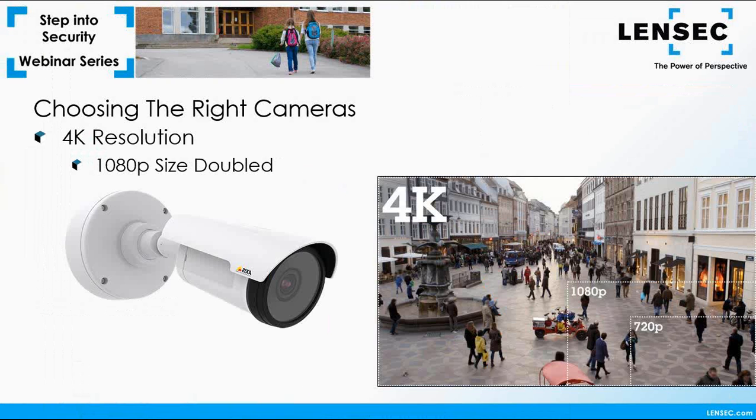In short, using a 4K camera in place of a 1080p camera will roughly double the pixels per foot in the scene. This means you'll be better able to make out facial details or a license plate in comparison to a standard camera or a lower grade megapixel camera. This Axis camera can provide 8.3 megapixels at 30 frames per second. Manufacturers are pushing resolutions up to 12 megapixels, and Sony has even announced a 20 megapixel surveillance camera.